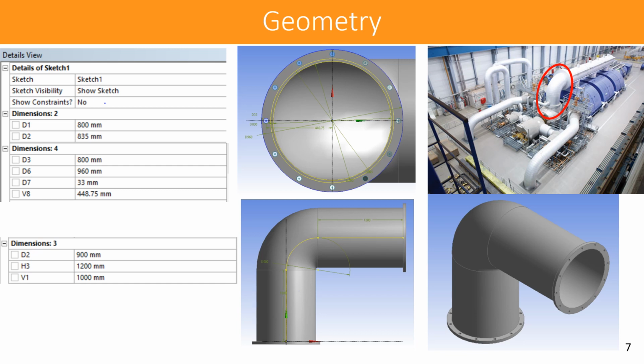It's secured with a bottom portion that is 960 millimeters in diameter and 40 millimeters thick, with screw holes that are 33 millimeters in diameter, and there are 12 holes on each port, so 24 holes in total. The tube itself is swept up 1000 millimeters along the radius or along the diameter of a circle of 900 millimeters and swept vertically 1200 millimeters. And that gives us the shape of the steam inlet pipe.